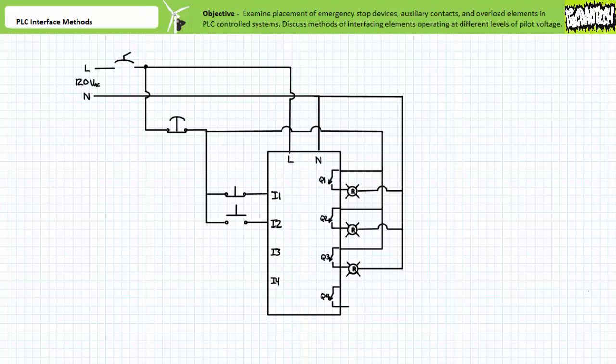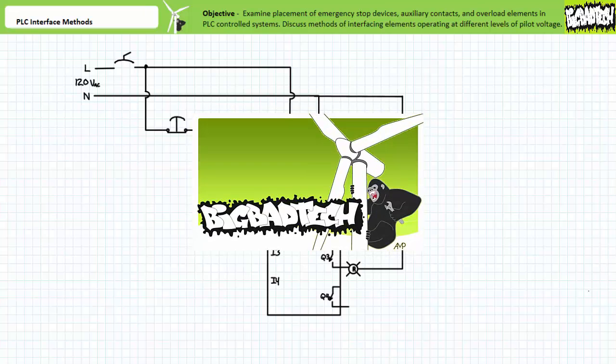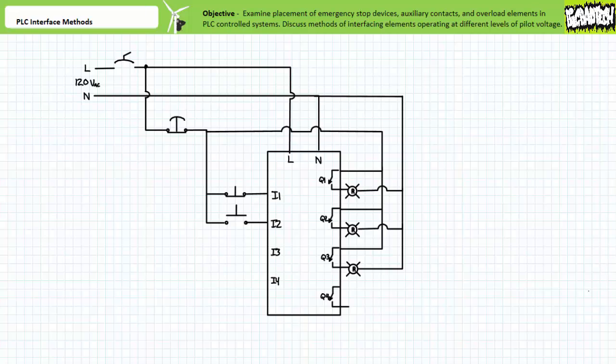Recall systems using traditional hardwired relay-based ladder logic simultaneously represent both interconnection and function using techniques as discussed in the ladder logic documentation lecture. However, since a PLC's principal advantage is its reprogrammable nature, one really only needs to schematically represent the hardwired connections. Very often, a PLC-controlled system represents this schematically as field inputs simply disappearing into the PLC and outputs selectively energizing or de-energizing the field outputs. However, this gives no indication as to what opens or closes these outputs.